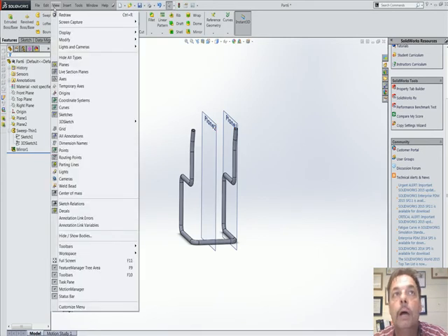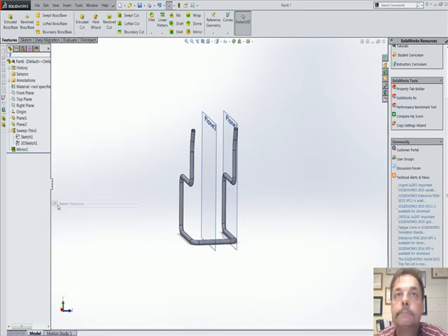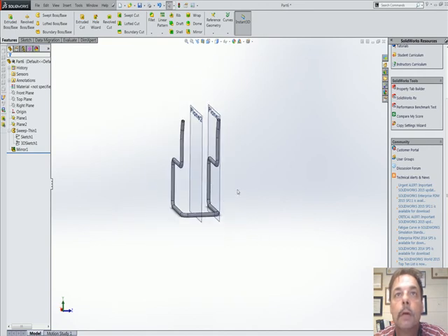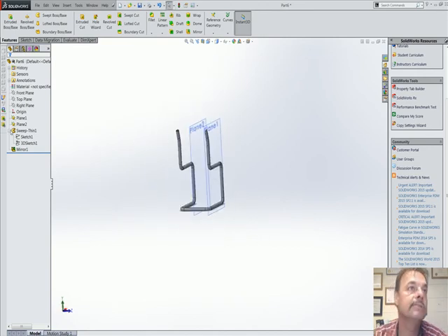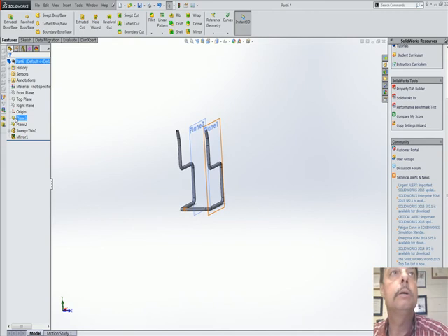Now, if you have any questions, let me know. Basically, that's all there is to it. You create two planes, one for your path and one for your profile. You sweep it, okay.